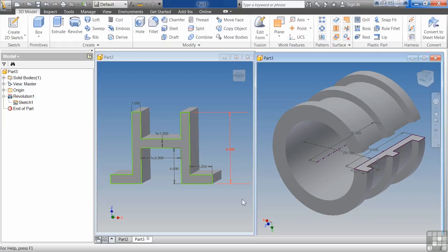When you create a new part, the initial sketch is the basis of your 3D geometry. After the sketch is created, you create a sketch feature, such as an extrude or revolve, to create 3D geometry from that initial sketch. When you create a 3D sketch feature, the sketch itself becomes consumed and becomes a 3D feature. Prior to this, the sketch is considered unconsumed and can be used for any sketched feature.